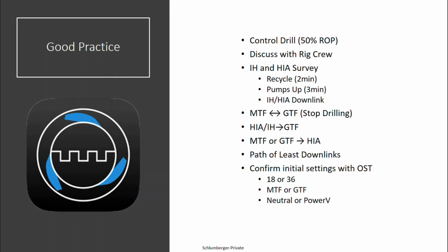Also good practice is if it's your first time working with the driller or the rig crew, before you initiate the downlink, to let them know if someone's safety or equipment is going to be damaged if you continue with the downlink, that it's no problem, abandon it and do what you got to do. We can get the downlink later. On the same note, if it's something not crazy and we're mid downlink, maybe don't answer the rig phone or ask your crew not to bug us for another 2 or 3 minutes.